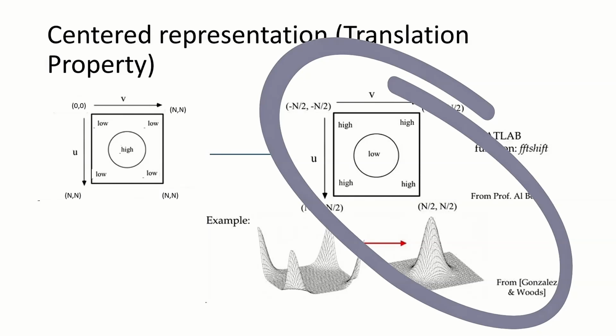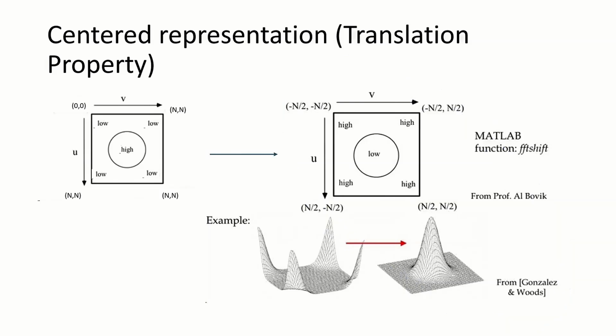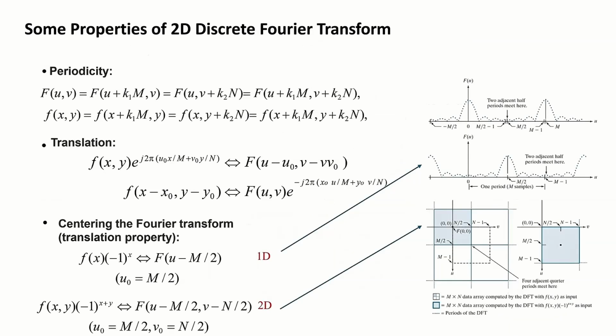So I'm able to take this. In the previous one, you can take the Fourier transform unless I do the shift. Yes, we are doing shifting, but it's indirectly in the time domain. First, we have to multiply with this, and then take the Fourier transform, so it will give me the shifted version. Not like taking the transform first and shifting. No, that will be difficult. So first multiply. This is easy.